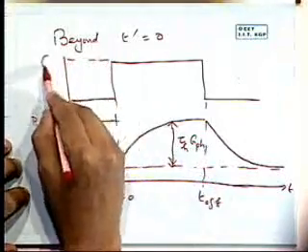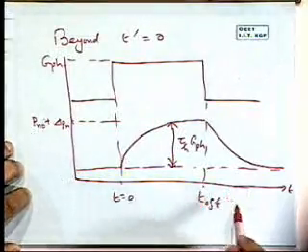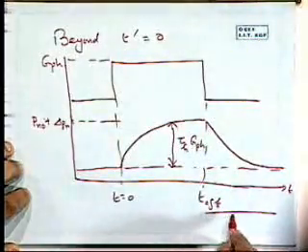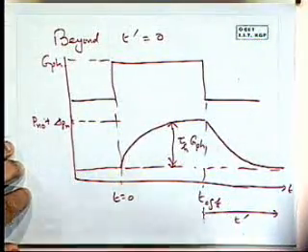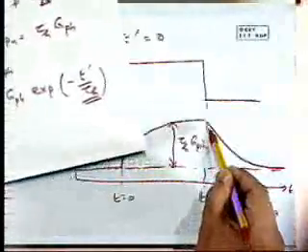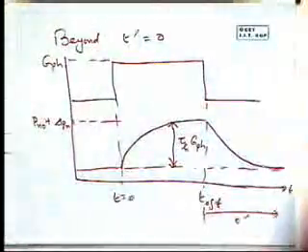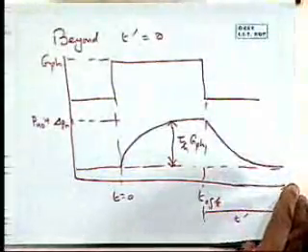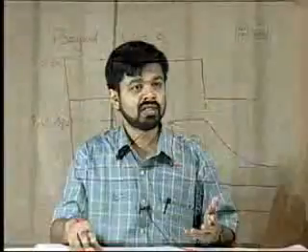Okay. Remember, t' is starting from this point. So on the t' scale, which we have written for that equation, t' begins from here, from t_off. So this equation that we have in terms of t' describes this behavior. Okay? So this is what we would expect when we illuminate a semiconductor of a particular type, n-type in this case, and watch how the minority carrier concentration increases, as we saw earlier, very drastically, some 10 to the power 12 times, and then over a time constant of tau_h, it decays back to its equilibrium value.